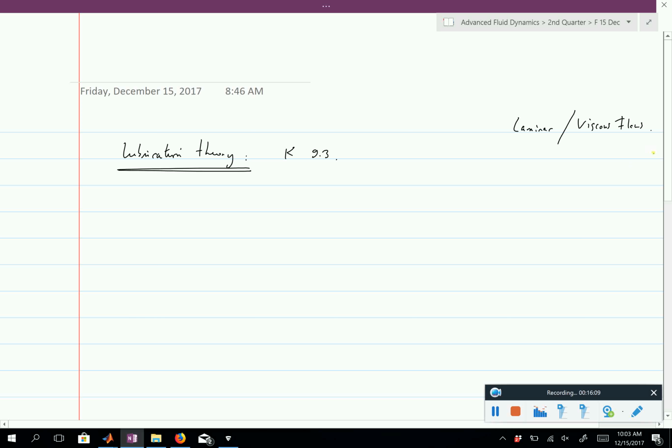Our first discussion of viscous flows had to do with unidirectional flows, because the flow was unidirectional, even though the Reynolds number might not be completely zero. You don't have the effect of inertia, and you only have the viscous term left. We'll discuss another application where the inertial term drops out, and you only have the viscous term left.